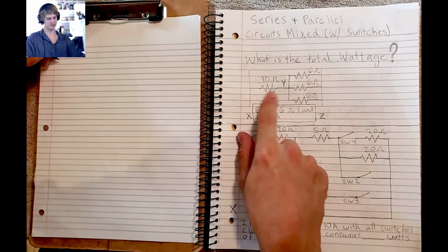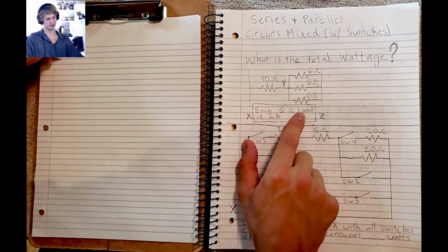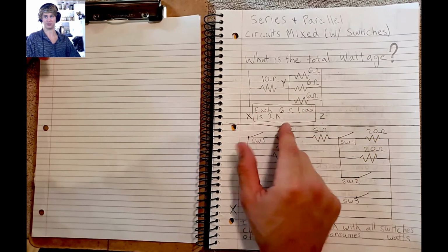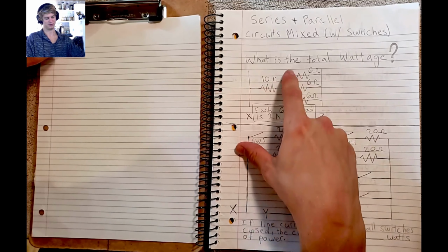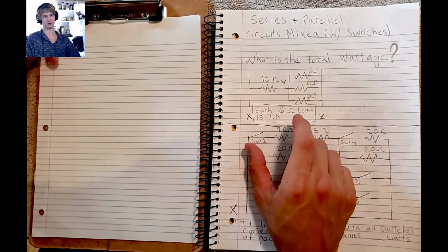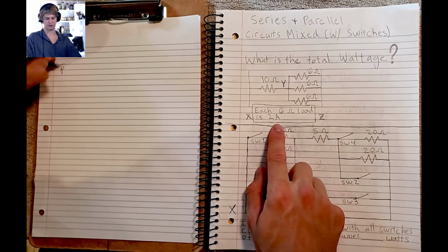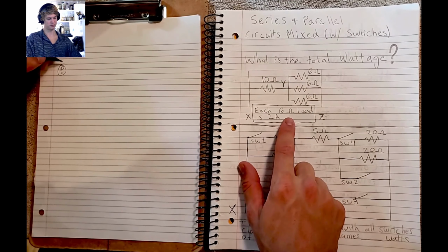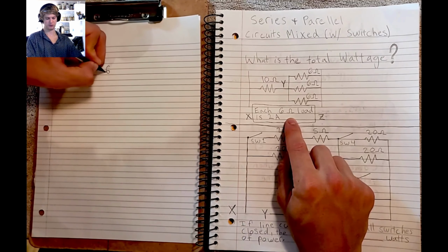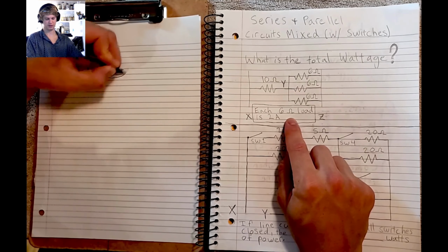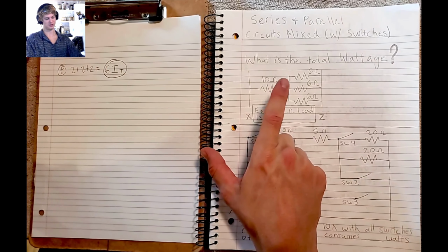Okay, so since this is wired in series and these are parallel, and we do see that we have the labeled current, let's at least figure that out. The resistor that's wired in series to the 3 that are wired in parallel is going to have the same current. So first for the parallel section, I'll just write the P. I have 2 plus 2 plus 2, and that equals my total current. And again, that's also my current now for this 10 ohm resistor.